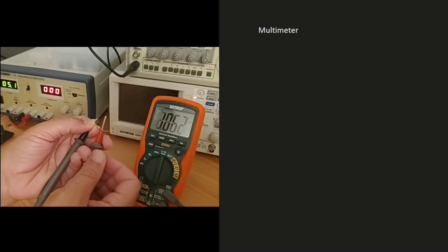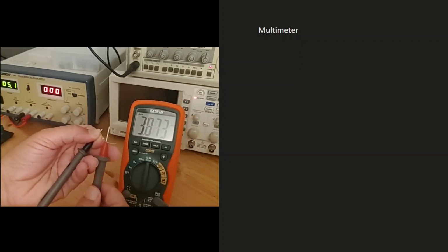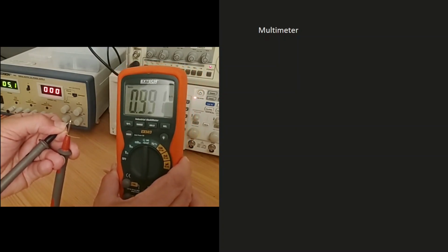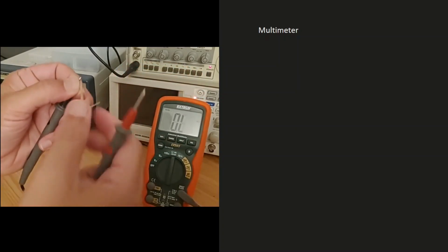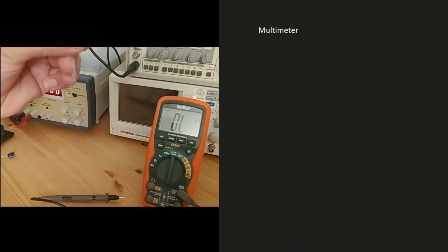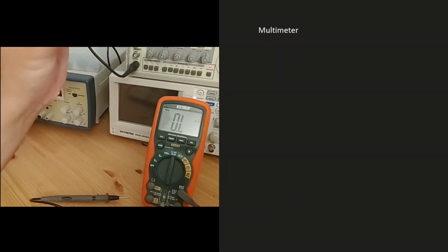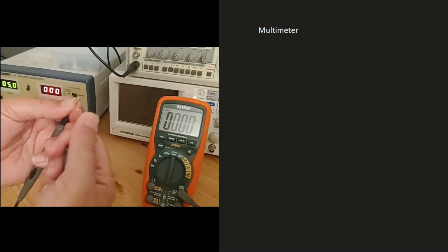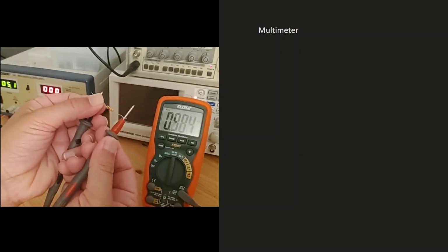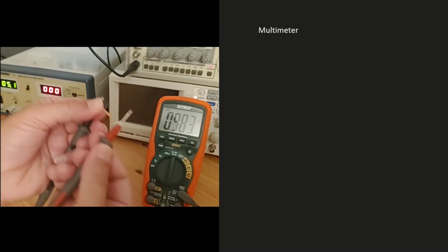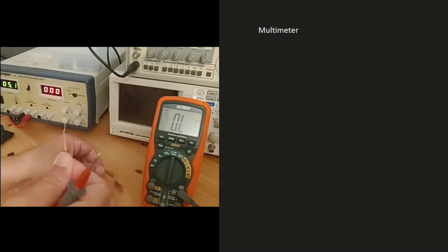Now here, I would like to show that we are measuring right now a value of 984 or 991 ohms. And this is actually a resistance value of 1 kilo ohm because it is brown, black, red. So brown, black, red means 1000. So that's 1 kilo ohm resistor. And we can see from the multimeter, when I measure this resistance using the probes like this, we can see 983 ohms. So this is how we will measure resistance.